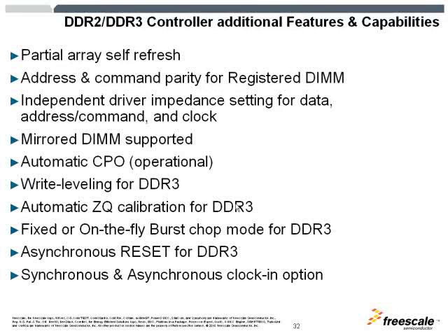There is a partial array self-refresh available, in case you don't want to refresh the entire SDRAM memory space. You may want to select a bank from that memory area and only refresh that, and let the other banks lose their content.